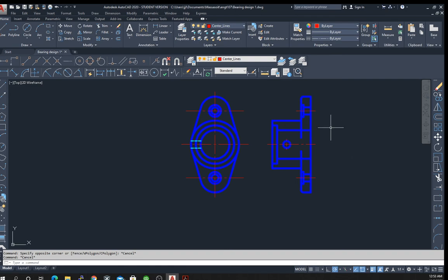The next thing we're going to do is we're going to delete these two extensions here. And the reason we delete these extensions is because when we do the cutaway, you don't see those. Those extensions are because of what happens here, the interface where this lip is going to meet this circle. And when you're doing a cutaway, you don't want to leave that as a hidden line. You just want to get rid of it. So we're going to delete those.